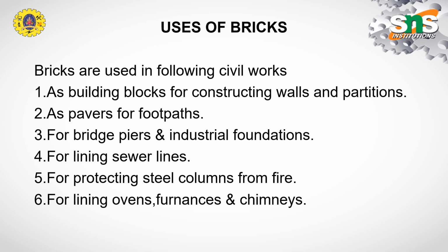It is an architectural form. It doesn't need to have any load bearing capacity. Only some properties need to be satisfied, like the absorption test. It doesn't need the mechanical and physical properties of the bricks made for constructing walls.